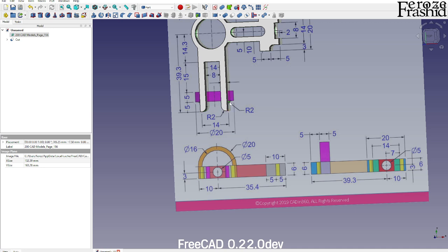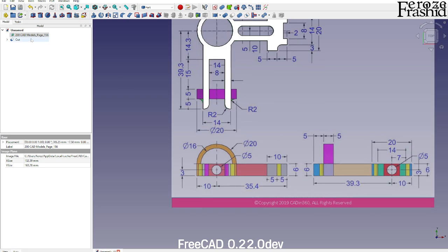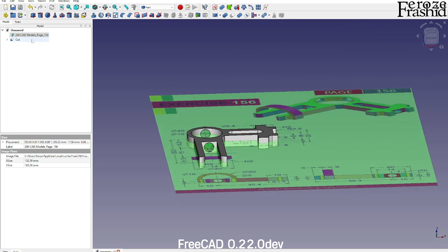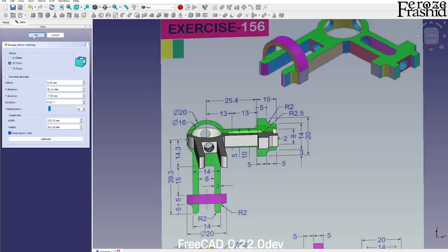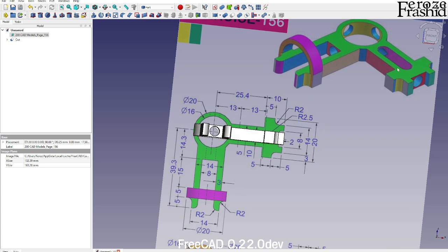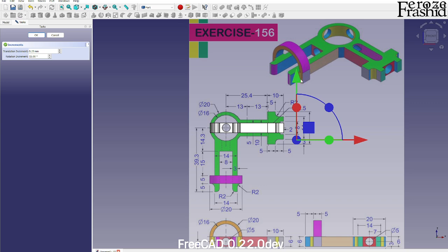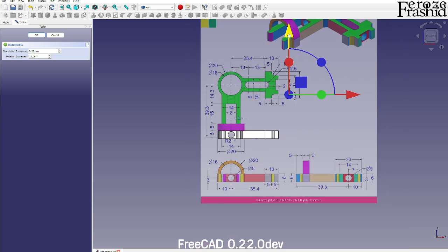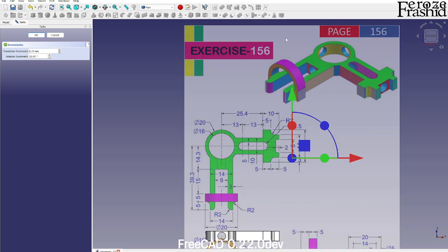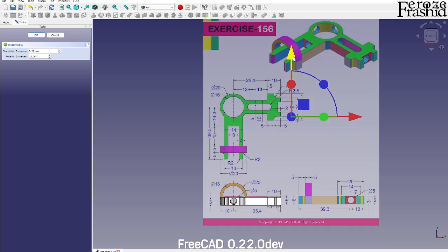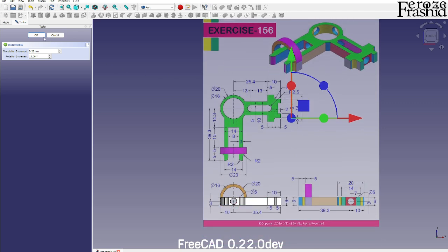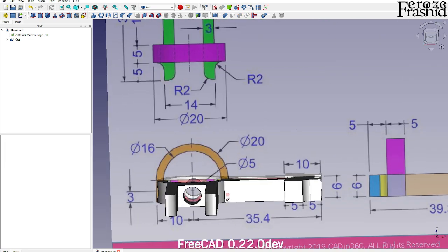So what I want to do is build this arch and then extrude that, right? So that arch is going to be on this face, XZ. So let's go ahead and take the image to XZ plane. And maybe, since we are using it anyway, relocate it real quick so it won't confuse us, rather it will help us. Okay, there. So we got that.